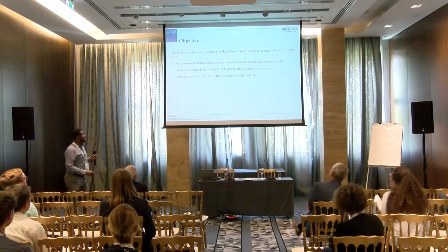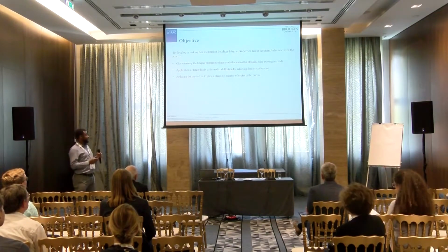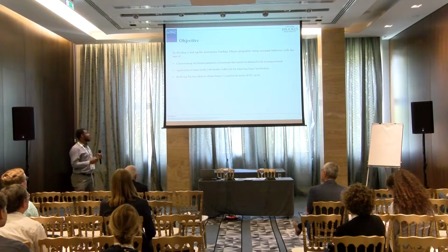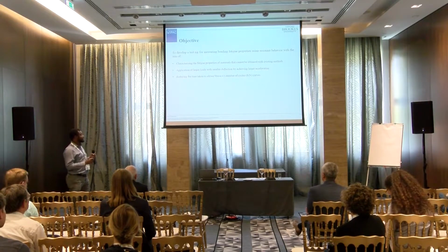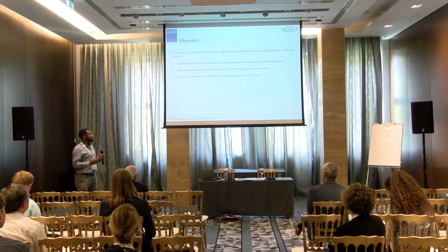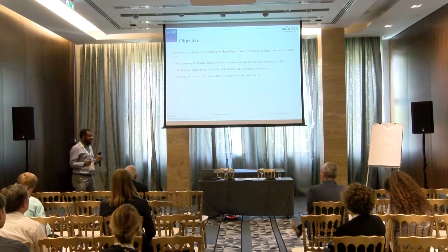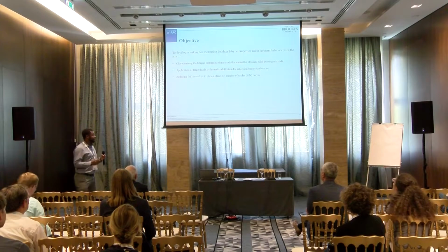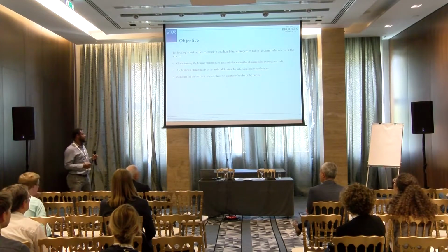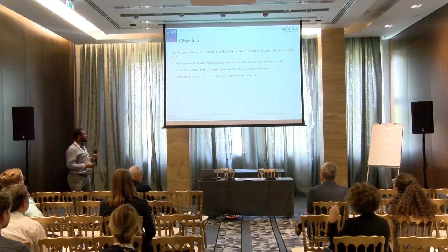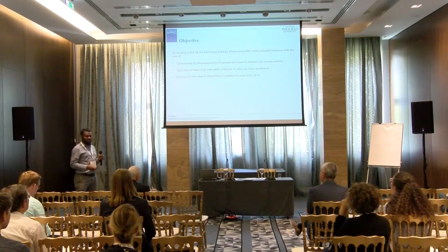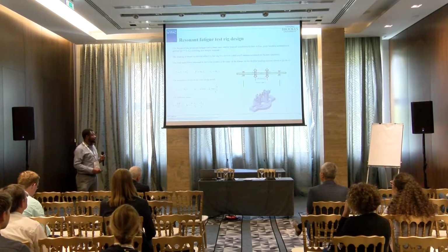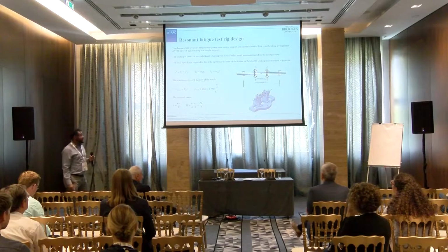Objective: to develop a test rig for measuring bending fatigue properties using resonant behavior, with the aim of characterizing the fatigue properties of materials that cannot be obtained with existing methods. Application of larger loads with small deflection by achieving larger acceleration. Reducing the time taken to obtain the stress versus number of cycles to failure, the S-N curve.